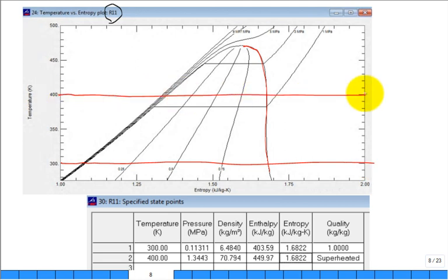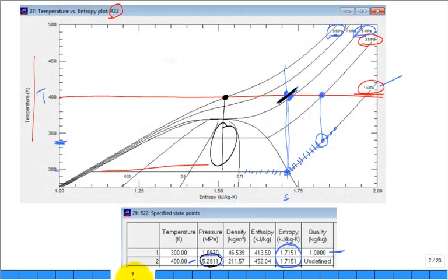Okay. One of the things I forgot to point out back here, most of the time, if you look at this refrigerant, if you really have a heat source at 400, you're going to be supercritical. Yes, if you had a pressure of only 1 or so right in here, you would go through a distinct phase change of boiling or evaporation, where there was definitely liquid and vapor, and under the presence of gravity, liquid sinks to the bottom of my container, where then it generates bubbles and pops out. That's boiling. You know what I mean?